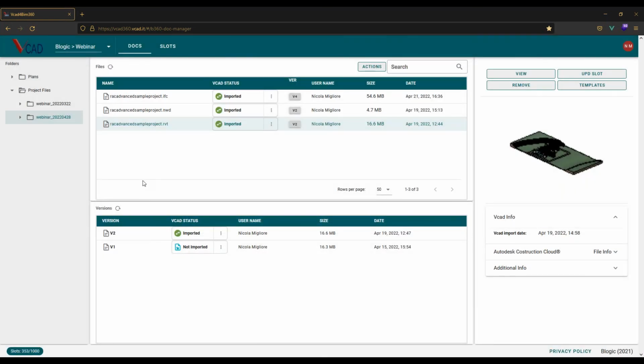Also, with Revit, it's possible to federate multiple Revit files through Revit link files. Vcad is able to manage Revit link files, and I'll have you note they count as a single slot, so you're actually able to bring in information from different disciplines all into a single slot and in a single report. However, levels from rooms, specifically rooms, require a little working with if you're trying to achieve that information. It's not as intuitive as an IFC file.